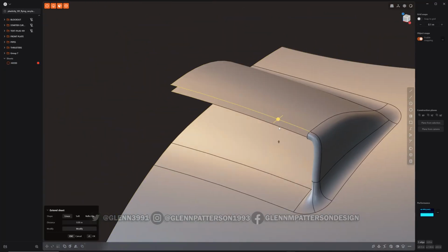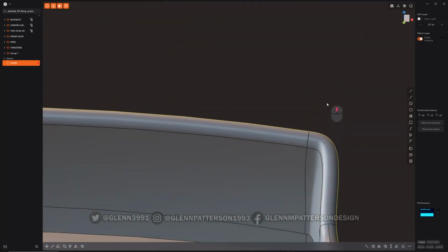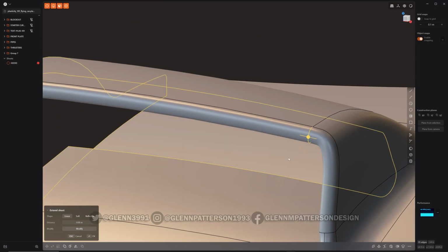And we're going to do loft. Cycle it to G2. Okay. Let's see if this bad boy will join together. Okay, there might be a gap there. Let's run our boundary edges. Yep, there's a gap there.